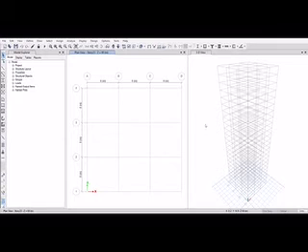And here we do not need to click on modify shear rebar, so click on OK. And again select the beam and click on add copy of property. Change the property name to B600 cross 400 and change the depth to 600 and width to 400. Click on OK.